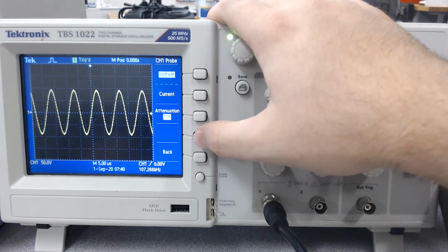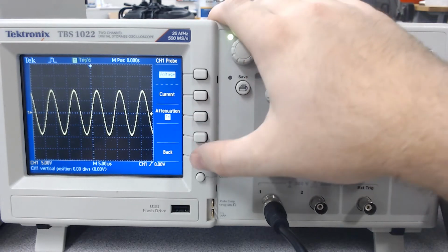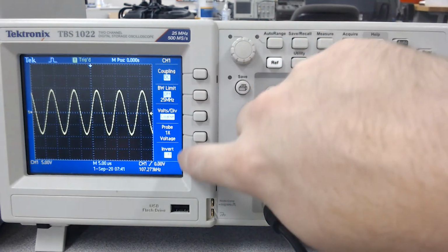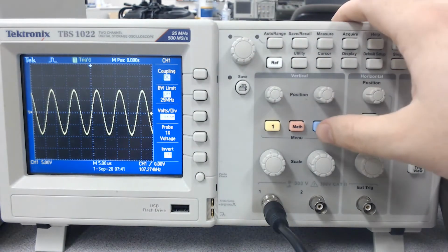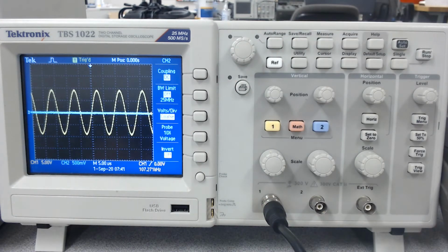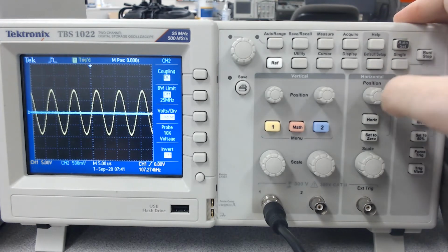And so we can actually hit the button next to that and cycle through. Now that's at 1x, so then we hit back. There are 2 signals on this oscilloscope that at times we will use. If you change the probe to 1x voltage, anything in yellow is for channel 1. If you use channel 2, it's actually at 10 times voltage. This can really screw up your measurements, because sometimes one of your answers is significantly higher than the others, and it's because you didn't adjust both of them. So whenever you hit the default setup button, that's kind of what you're going to have to do.